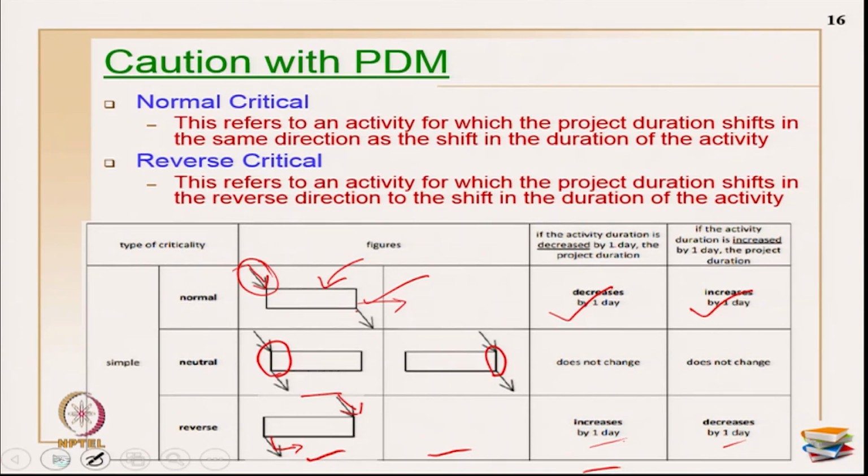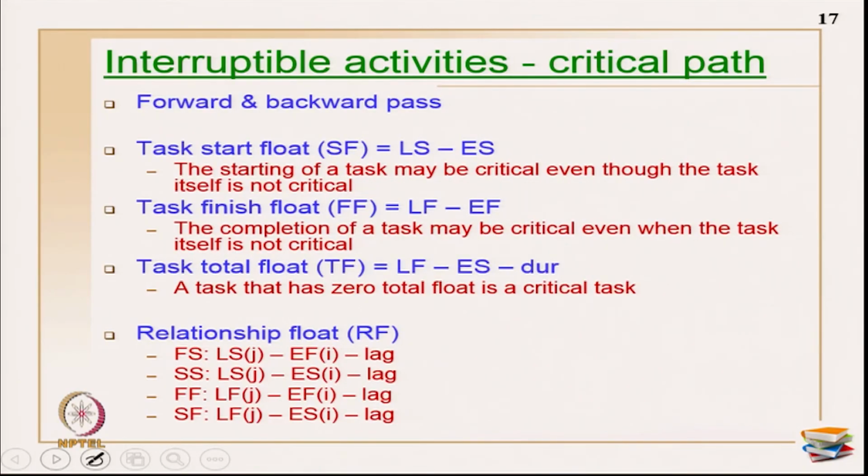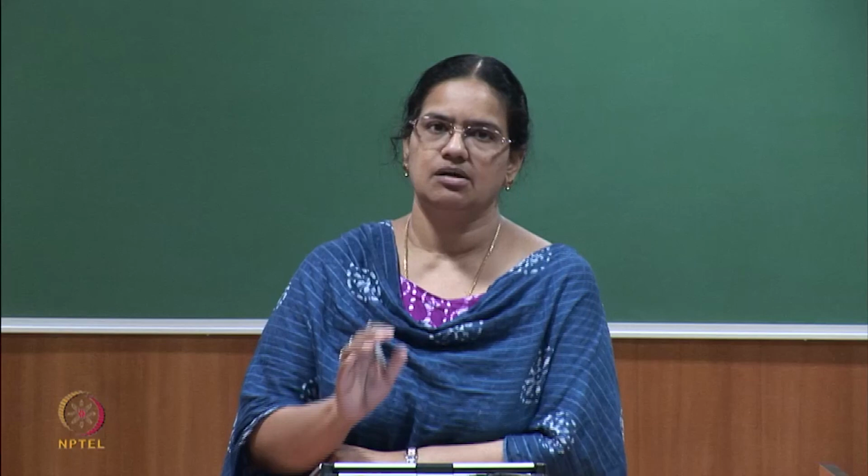Okay. So, you have to be very, very careful with contiguous activity execution. Only on certain characteristics you have to be very careful. Like this, we have bicritical, multiple criticals. There are so many types, we have to be really cautious with the PDM analysis. Okay. The next is interruptible activity execution. This is a little tedious type of calculation. Some researchers said that when you are using a PDM network with all the issues of overlaps and so on, then there should be a sufficient number of breaks between the activities' execution. Otherwise, there is no fun in developing a PDM network.